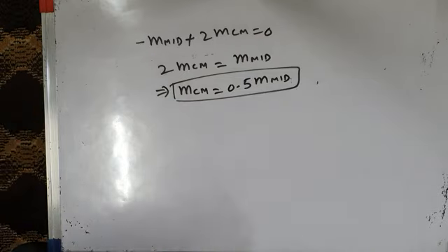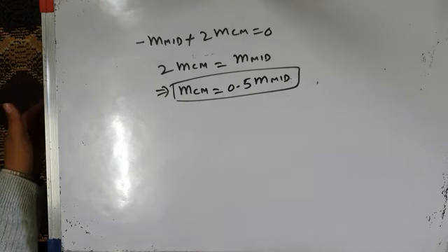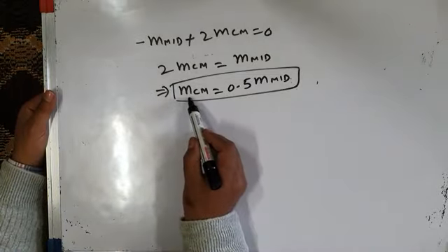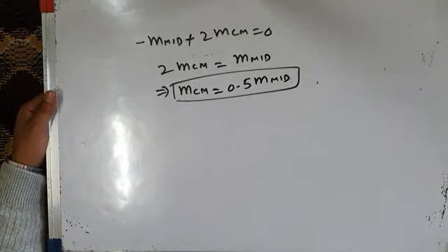Your inverter output voltage will increase by about 15.5%, and T0 will be equal to T7, the null vector times will be equal, and it will give the least harmonic distortion in the voltage. Same results as produced by conventional space vector PWM. So let me see how we can generate this common mode signal MCM.